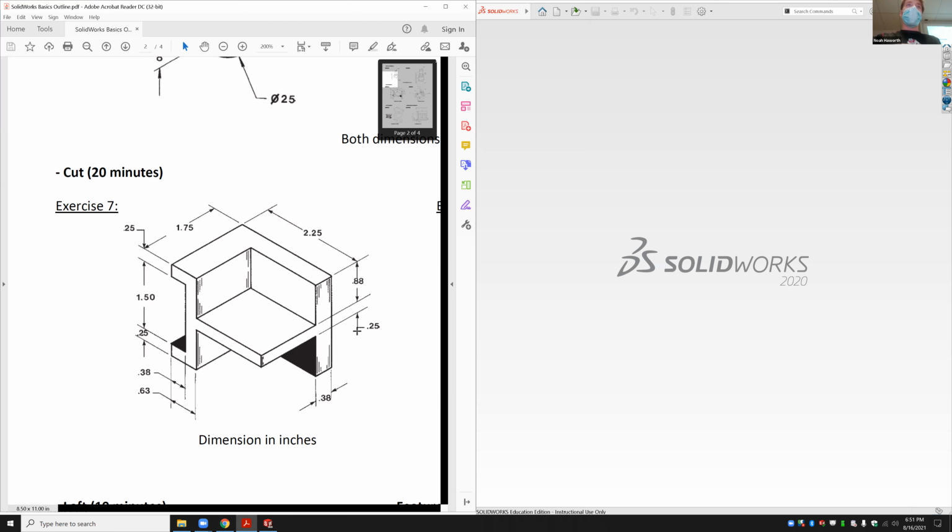it's interesting if you do the math. First off, we're going to assume everything is symmetrical about the mid plane right here. If you make that assumption, what is the overall height of this part? By the way, what I'm talking about right now is outside of the scope of CAD, but it is relevant for this specific problem and also just for knowledge in general. The height would be 2 inches. Yeah, and you got that by adding up these dimensions right here.